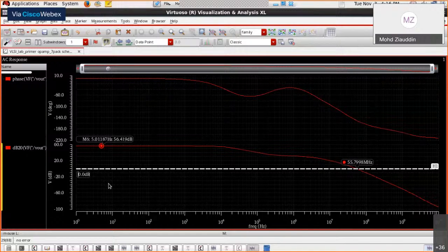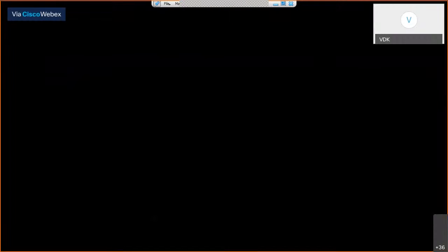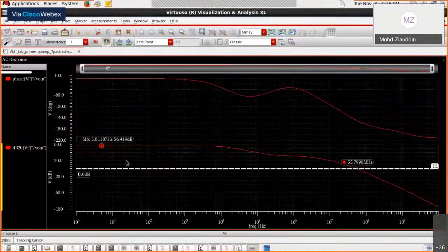Then can we do a separate characterization for this tail device using a different VDS, which is more appropriate? What I meant is, when you are characterizing the devices from a foundry PDK, we parameterize W and L over different discrete sets of values, or bins.